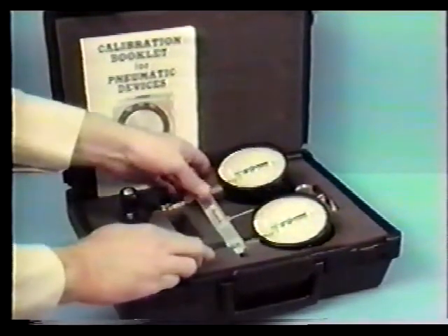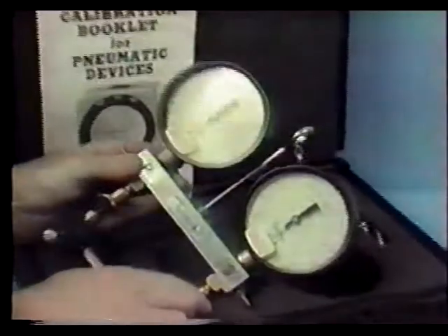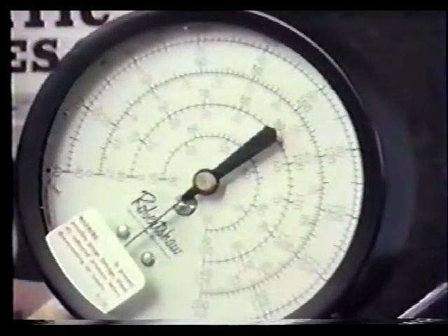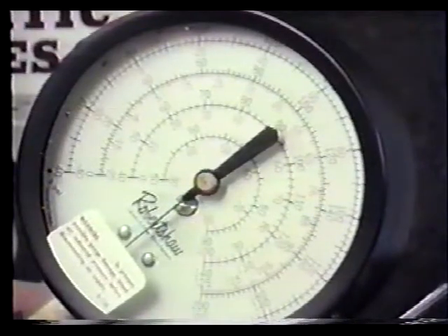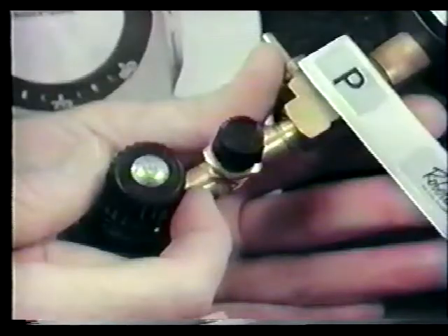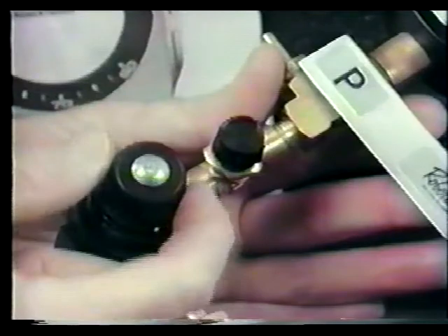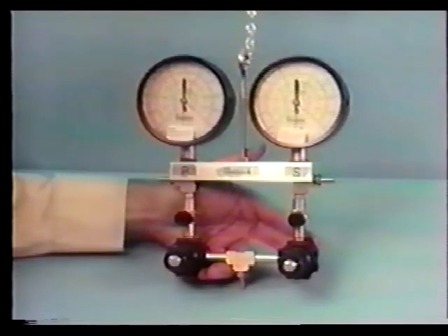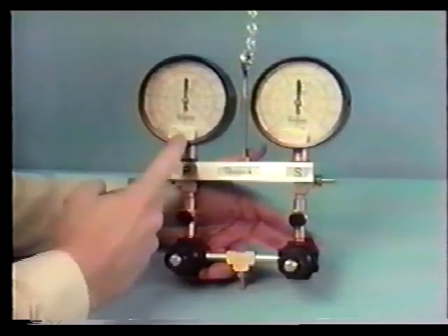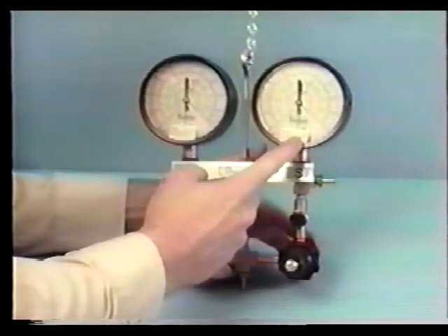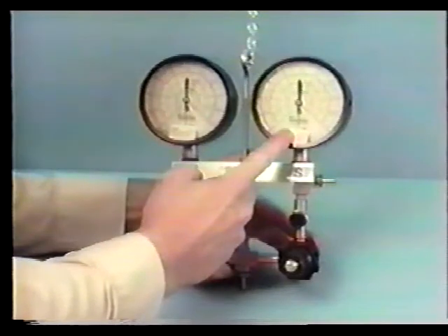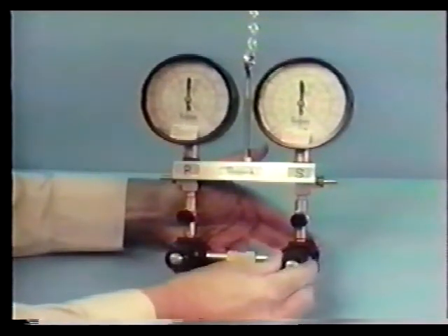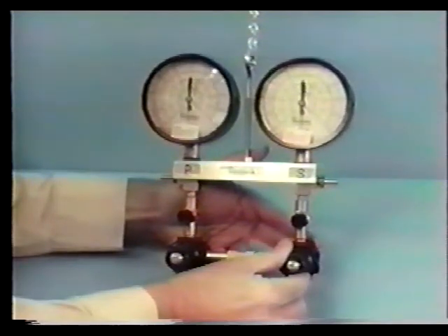We will utilize this kit because it provides a handy frame of reference for producing inputs to the receiver controller. We refer to this type of calibration as bench calibration because of the ability to adjust the inputs to any value desired. The most predominant feature of the receiver controller calibration kit is the multi-scale gauges that allow you to read temperatures directly from the gauge scales. The next feature is the pressure regulators used to adjust the output pressures indicated on the gauges.